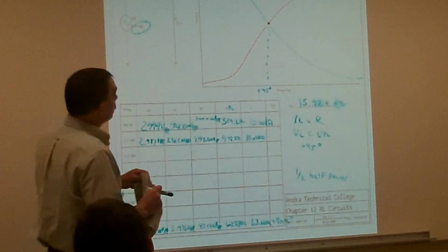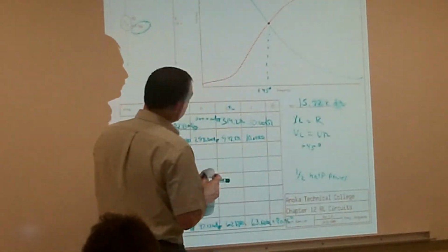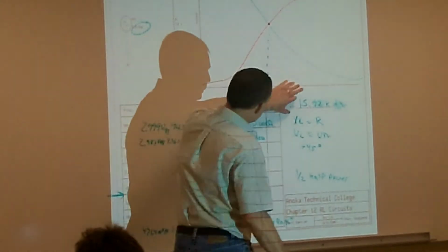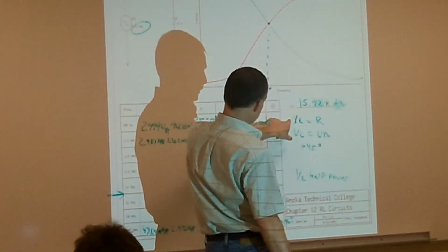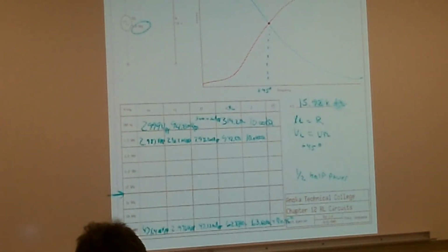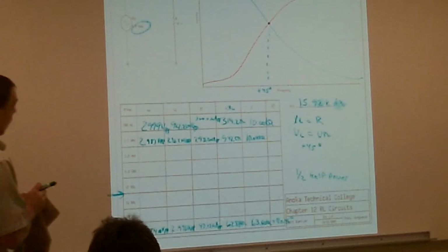That should be almost 45 degrees. That's going to be almost 60. Okay, so you should always know. If somebody asks you what's your frequency cutoff, just look and see what the value of your resistor is, and substitute it in your formula. You can always calculate your frequency cutoff. All right, so